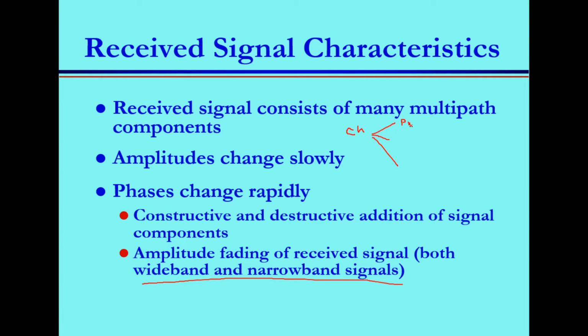Delay spread, the meaning of it is that your signal reaches the receiver at different time instances, at different channels. Due to what? Due to reflection from many objects located at different distances. Doppler, reflections from many objects that are moving, shifts the frequency. Fading, when all these reflections are reaching the receiver at the same time, they can be added constructively or destructively, making the amplitude fluctuate.